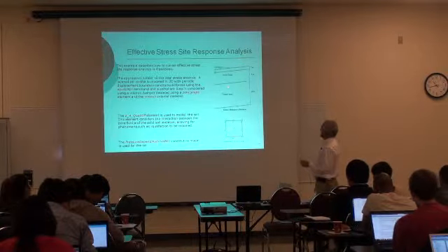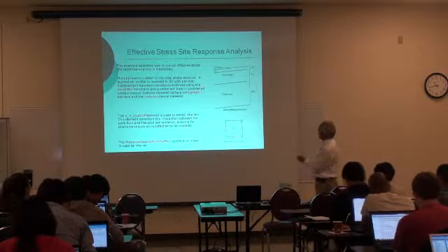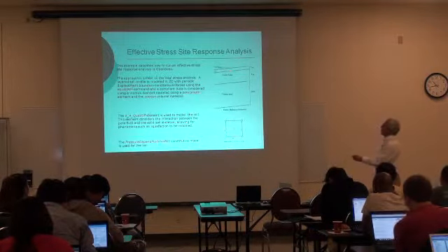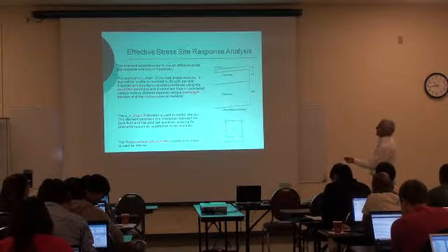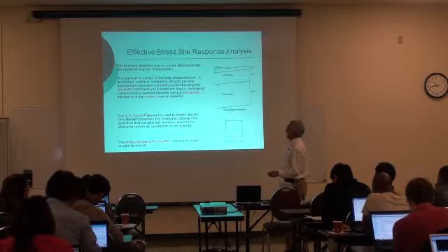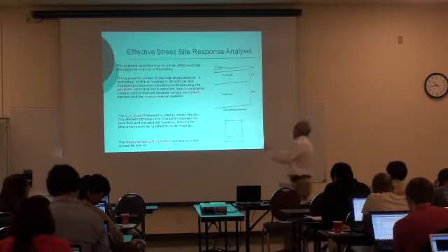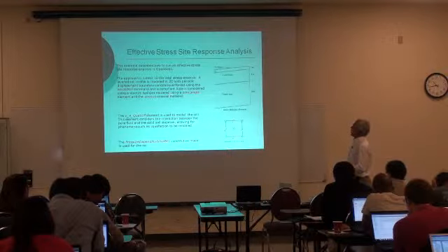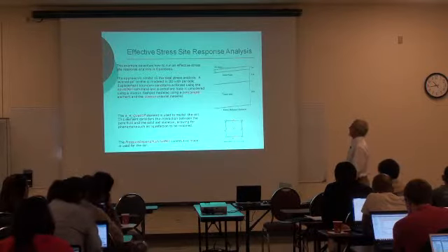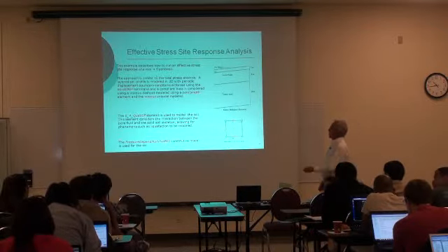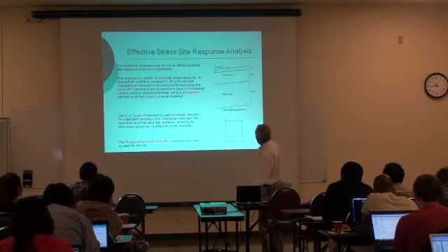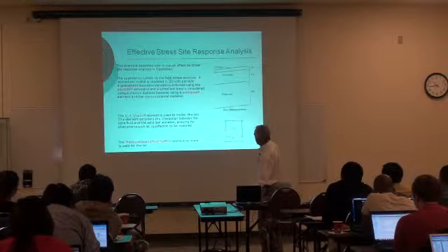The other thing that we did is to start moving a little bit beyond the simple free field analysis. We wanted to model a free field analysis of a sloping ground, but now with effective stress conditions. We consider not only the behavior of the soil, but the soil under a liquefied state. For that, we use, again, the 9-4 quad element to characterize the response of the fluid and the solid. We use the zero-length elements in order to get the boundary conditions correctly, and the equal DOF. And we use the pressure-dependent multi-yield 02 because that seems to be a good one to characterize the response of the liquefied soil.